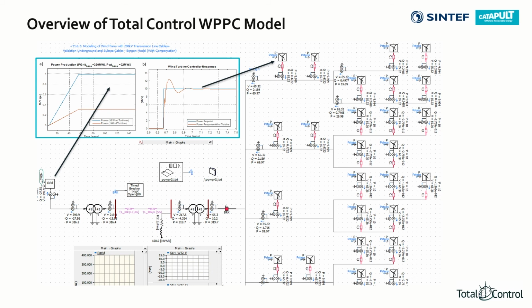As you can see, the wind turbine controller responds to a set point there of 10 megawatts, which changes for each of the turbines, and that produces the overall output as expected. So where we are at the moment is beginning to integrate the advanced wind farm controller model into this, and starting to run the tests between the two.